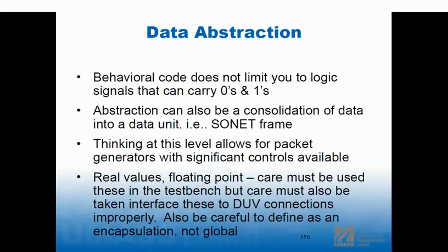Now, I think that if I have a scoreboard and I'm generating packets at that high level, I also want to get a high level result to go on the other side of the scoreboard, because I'm trying to match those data structures. And in fact, I'm probably, and I don't want to say always, going to keep the format of the input, the stimulus bus function model, the same as what comes out of the receiver, the detector. So when I check it in my scoreboard, I'm simply just looking for records to match.